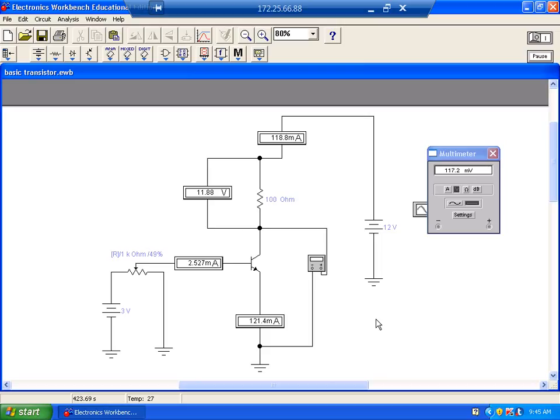And what's nice about this, if I saturate it, we can control a pretty good deal of current with a very small transistor, because the power that the transistor is dissipating is equal to what? V times I. Well, if V is really low, then I can be what? Really high. So when we operate these transistors between saturation and cutoff, then we can get a pretty good deal of current flow out of a small transistor.